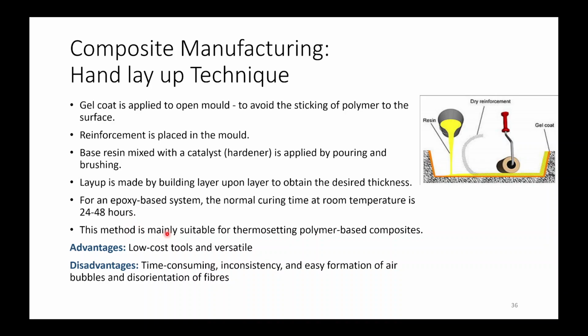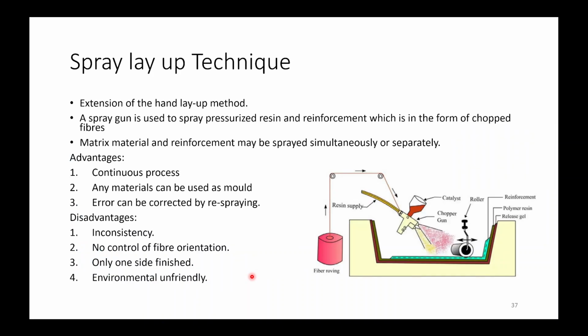This method is mainly suitable for thermosetting polymer based composites. Advantages are that this has low cost tools and it is a versatile method. The disadvantages are that it is time consuming, it is inconsistent, and there is easy formation of air bubbles and disorientation of fibers.